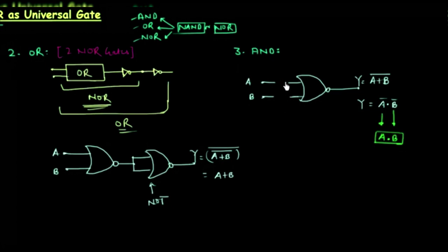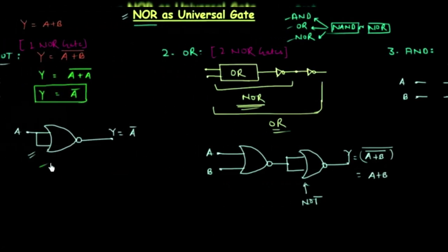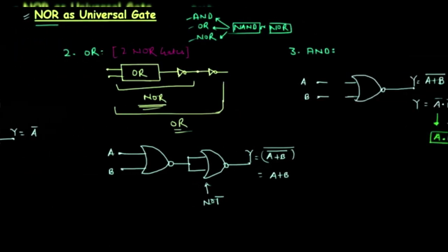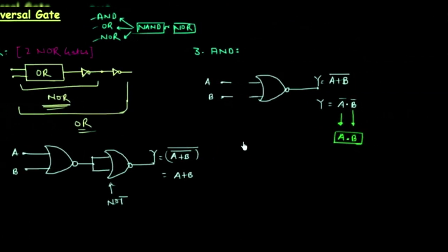So we'll do this quickly. We will complement the two inputs, and again I will use this arrangement here, because we are implementing the gates by using the NOR gate only. First I will complement A. So let's make one NOR gate here, and the two inputs to this NOR gate are A. So here we will have A complement, right? Then I will complement B, and the two inputs are B. So here we will have B complement.